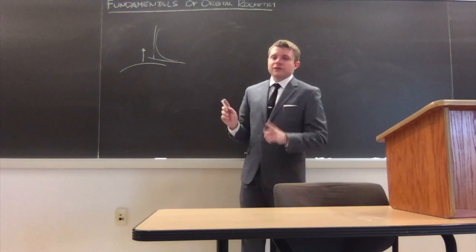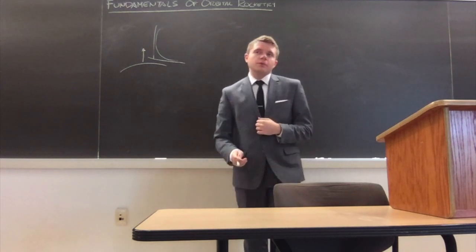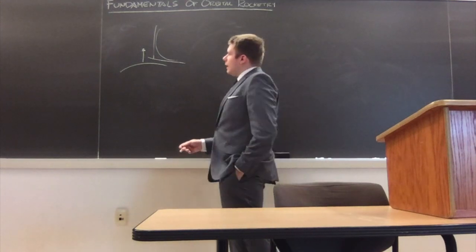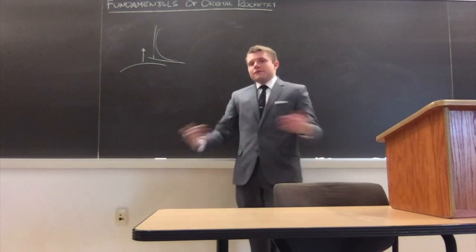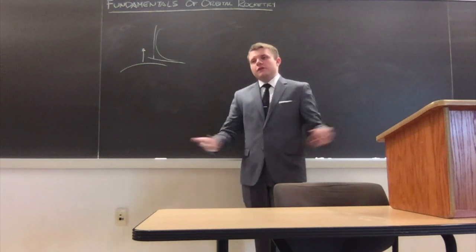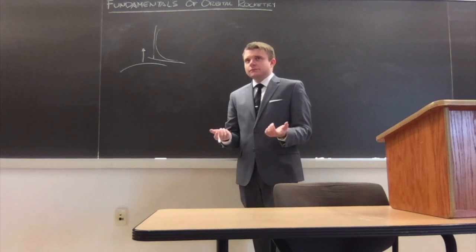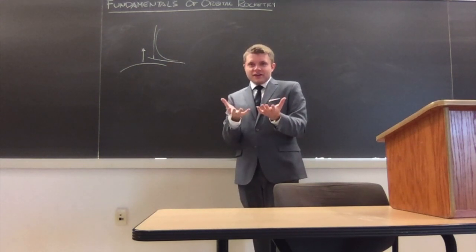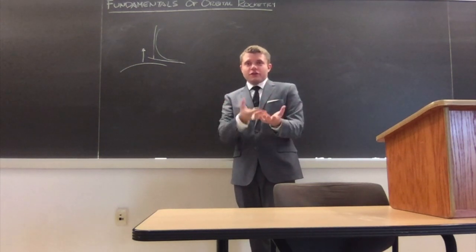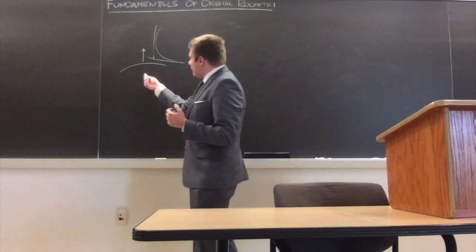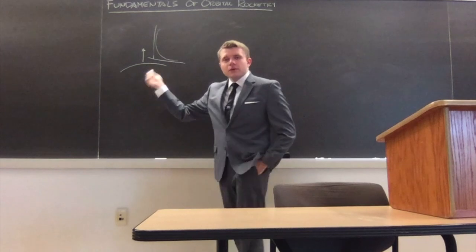That means you're actually accelerating upwards at 9.81 meters per second squared to cancel out the acceleration downwards at 9.81 meters per second squared. And what that means is that you're actually putting some kind of change in velocity into your system to keep yourself floating. That's something you have to consider across the entire burn time of your rocket. If your velocity points straight up, the more you have to deal with it.